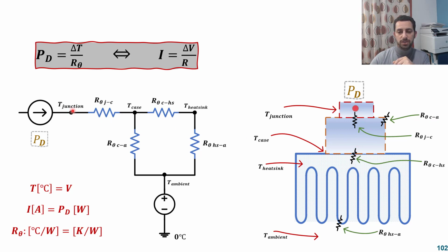So once we come to the temperature of the case, we have two ways: the case to the ambient, reaching the ambient temperature here, and also the case to the heatsink. And after going from the case to the heatsink, we have another one, which is from the heatsink to the ambient. And because this one was very large, I ignored it in the first graph. But here I want to consider it because I want to deliver my full view.